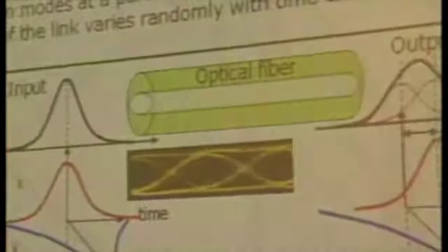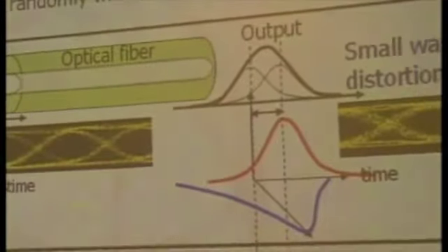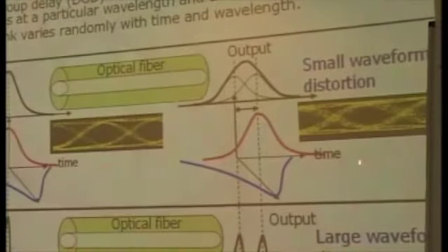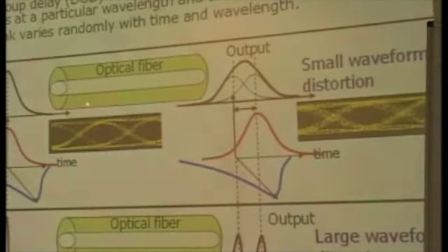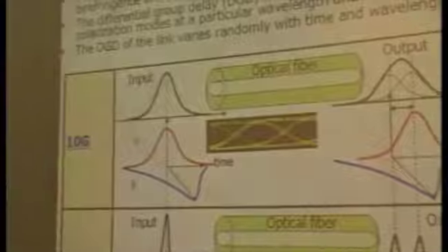Okay? Do you understand? So this is a so-called 1 dB penalty, we say. If there is no waveform distortion, -20 dBm received signal is okay to meet the performance of BER of 10 to the power of -12 or something like that. But if you get such a dirty or degraded waveform after fiber transmission, you will need 1 dB more power than this clear wave.